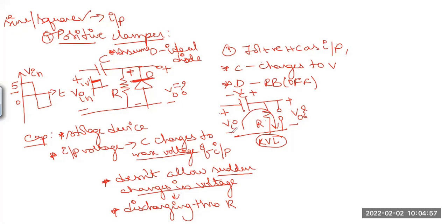So it starts here with minus. So I can write it as minus Vi plus, sorry, the next immediate voltage that you see is the capacitor here. So it is encountering negative first. So minus VC. Then the voltage across R, which is nothing but V naught. So I write it as plus V naught equal to 0. So KVL says that the sum of all the series voltages present in a circuit is equal to 0.